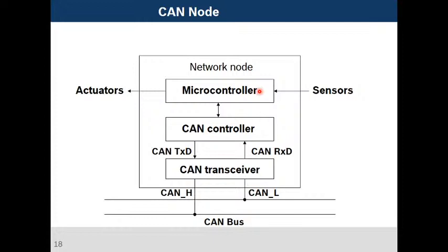We have microcontrollers from Atmel and Microchip, which will be physically connected to a CAN controller, and there are two possibilities: an inbuilt CAN controller, or an external one. For example, you have ADC sensor inputs.